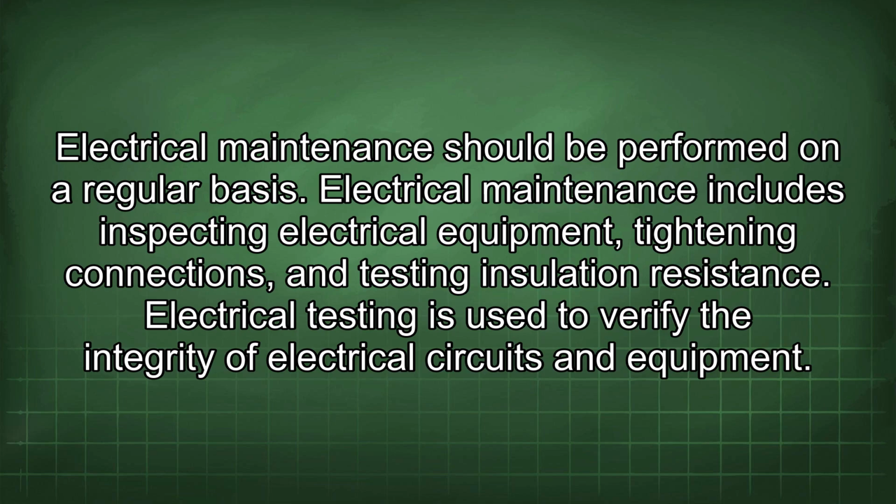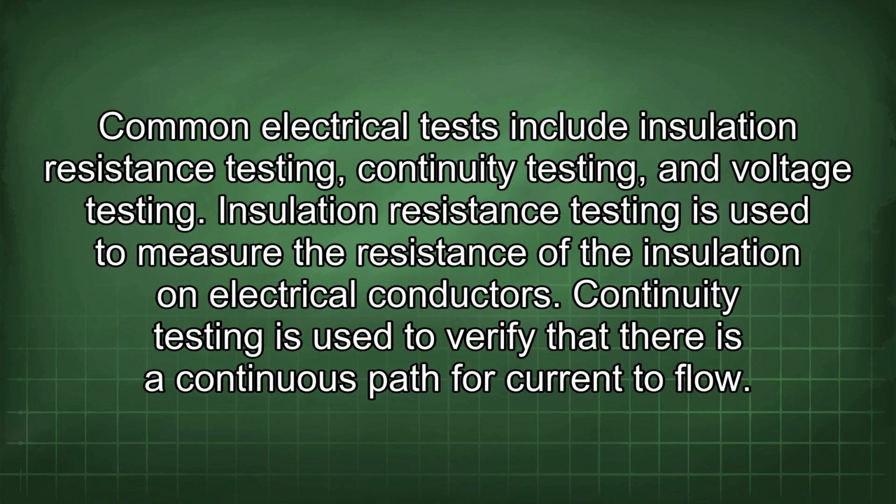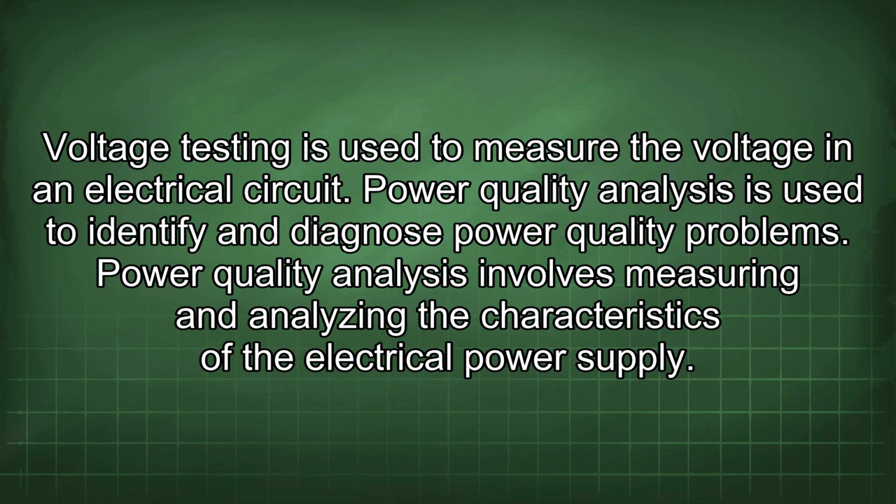Electrical testing is used to verify the integrity of electrical circuits and equipment. Common electrical tests include insulation resistance testing, continuity testing, and voltage testing. Insulation resistance testing is used to measure the resistance of the insulation on electrical conductors. Continuity testing is used to verify that there is a continuous path for current to flow. Voltage testing is used to measure the voltage in an electrical circuit.